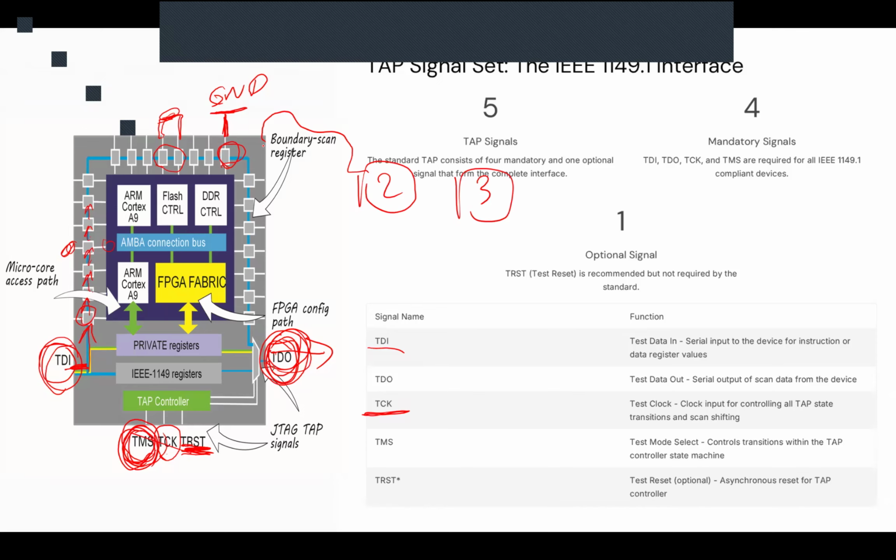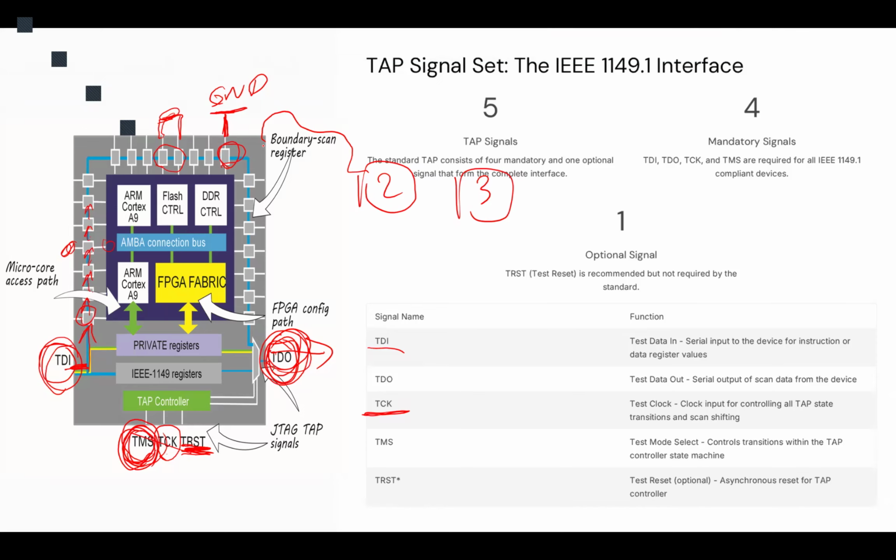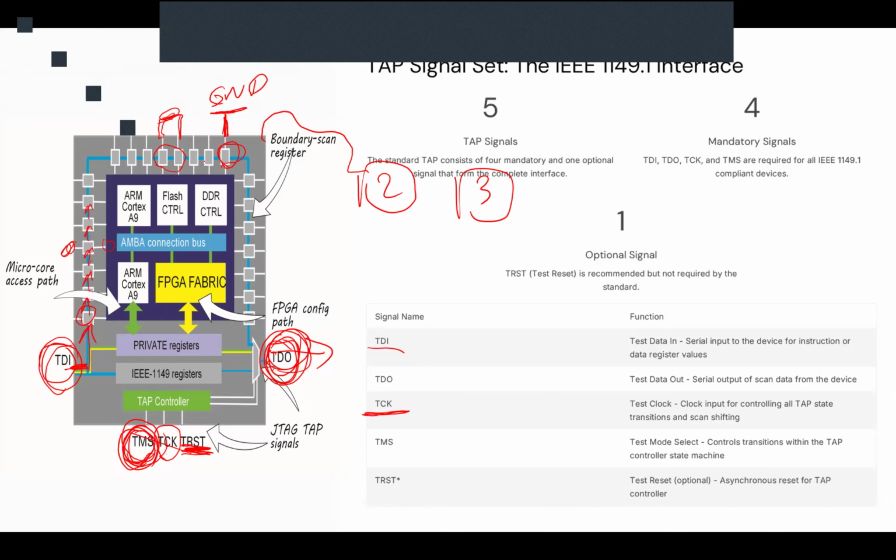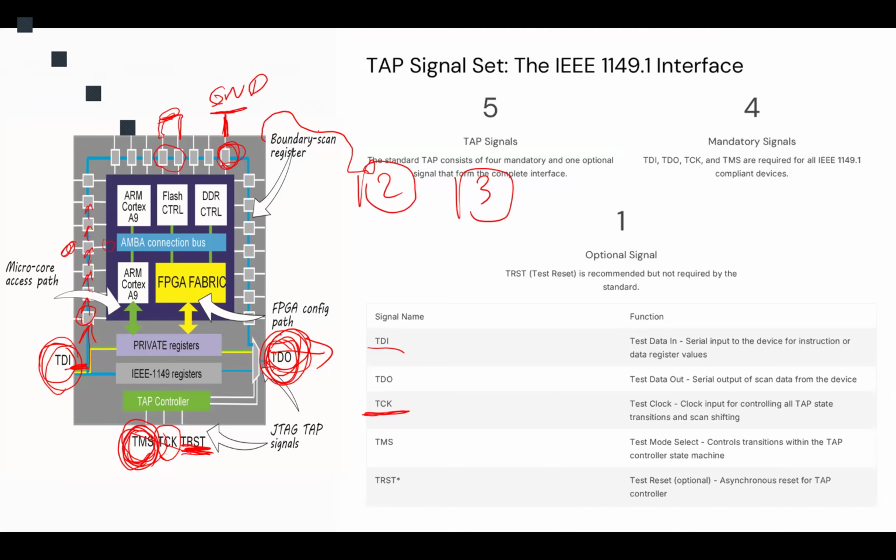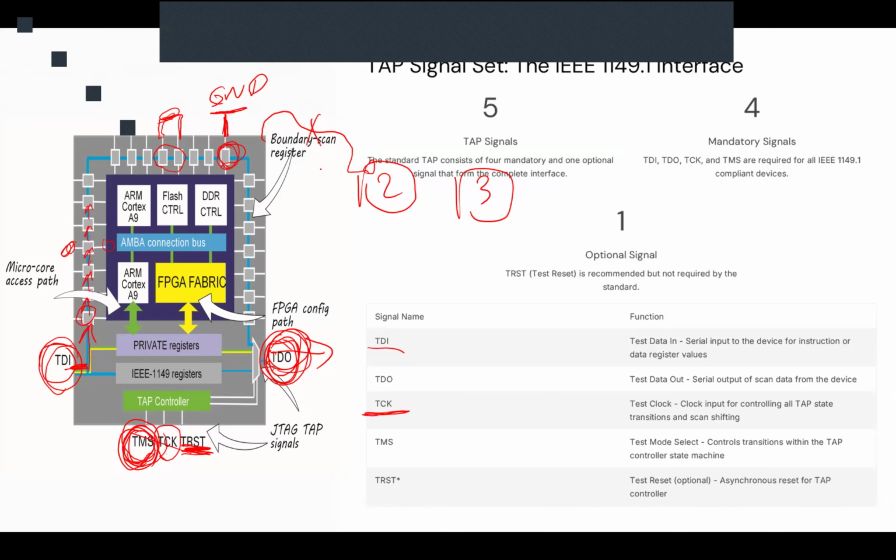And if we see any defects, for example, the first pin of this chip should be connected to the first pin of this chip. If we see during the test that these two chips do not always have the same value, that means this trace has a defect. This is an example of how this testing works.